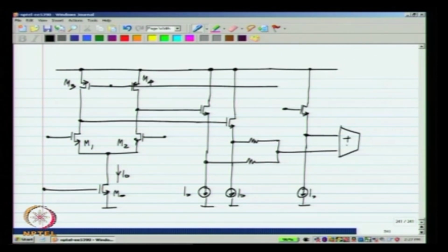And you use a transconductor to complete the feedback. Previously, I had used an op amp symbol here, but it is really a transconductor. You do not make a full fledged op amp in this case. It is really a transconductor because it has a high output resistance.